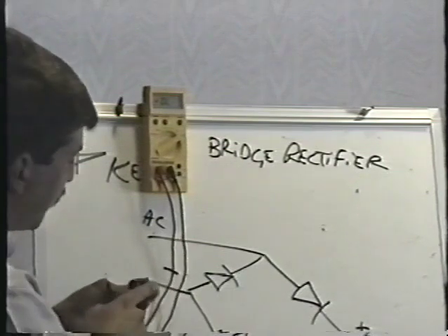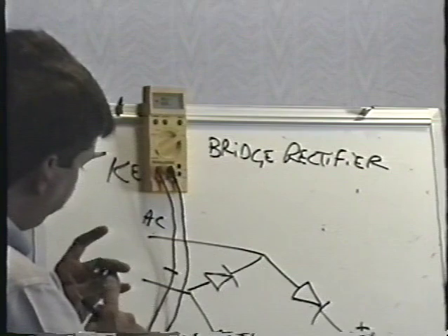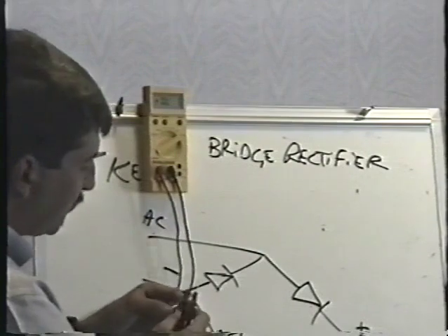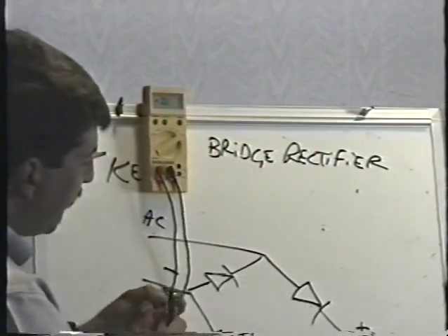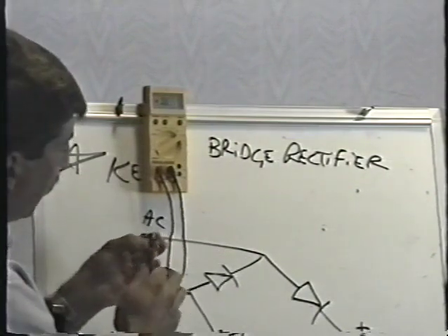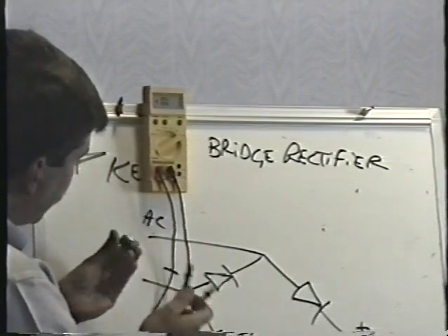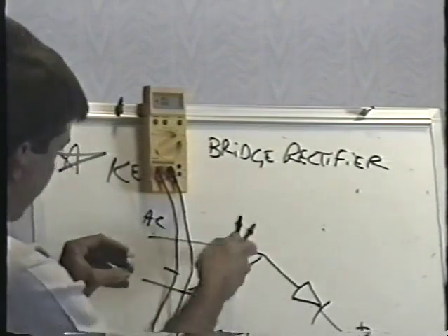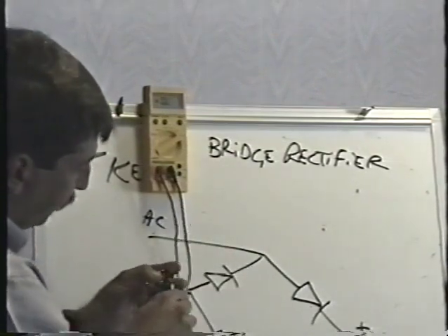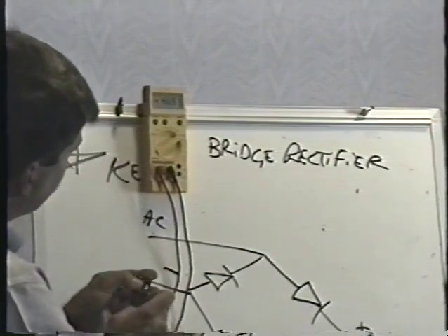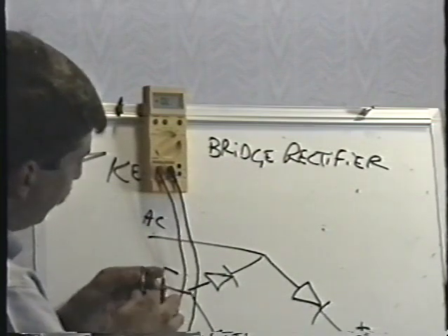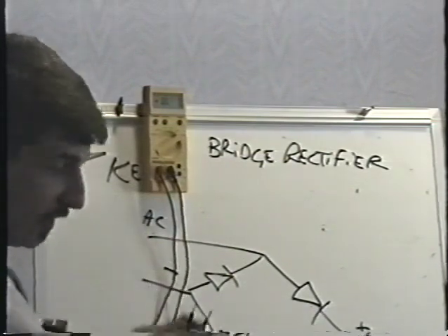So that one diode is good. This diode happens to be this one, or this one. I really have no way of knowing which it is. Now we'll rotate it 90 degrees and check the next one. Junction drop, 0.46 it says on the meter, open. So that one's good. This one happens to be the other one of these. I can't tell which it is, really. Next one, junction drop, 0.46, open. That one's good. One more to check, open. Junction drop. So this whole bridge rectifier is good.